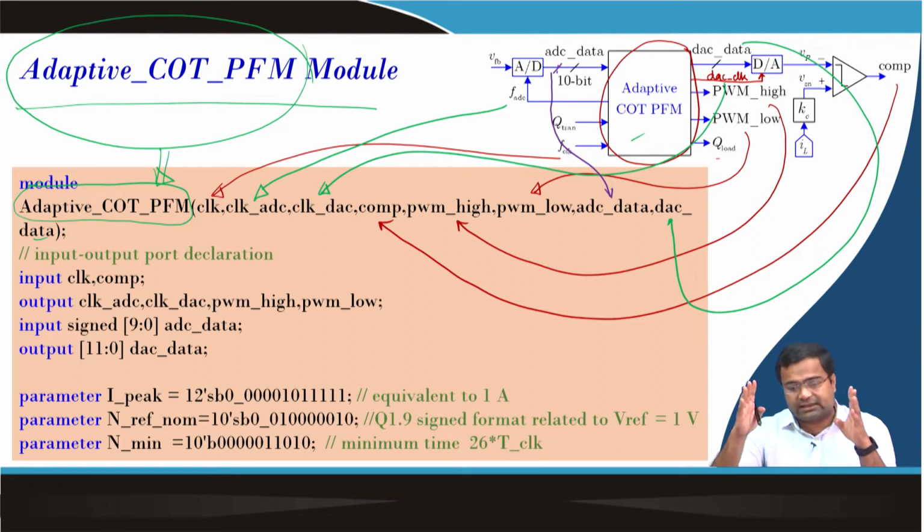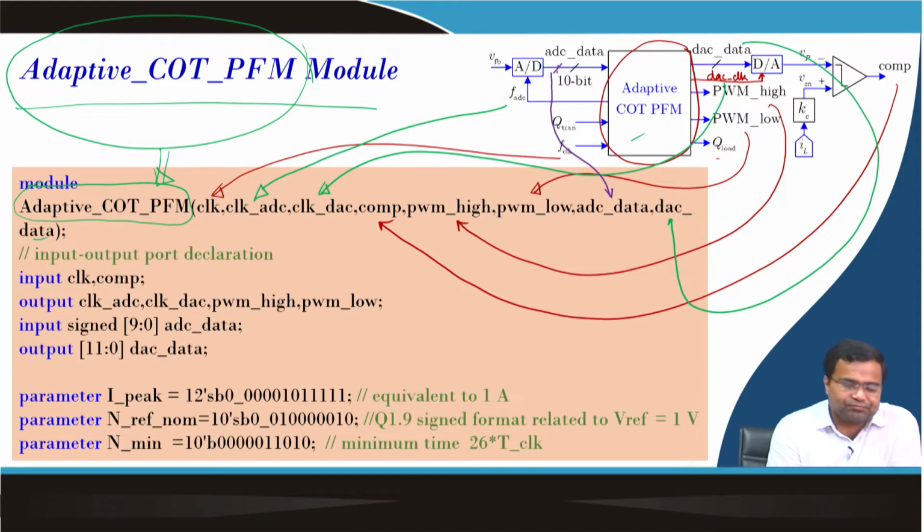And we have also discussed it requires a UCF file, user constraint file or the implementation file, and that I am not going to show because we have already discussed the procedure of running UCF file and so on. We want to synthesize the internal module which will be prototyped using FPGA. So, we have to declare which are the input and output, and from this picture it is clear, from the direction, which is going out, that is the output, which is going in, that is the input. And input also we have a vector data, that is the ADC data sign, and the output,